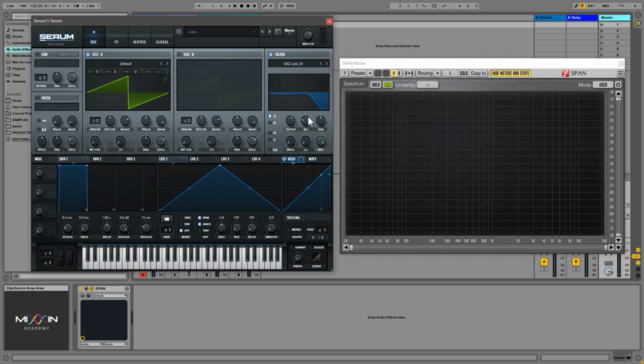Now, another really important parameter we have for a filter is the resonance. The resonance is the amount of boost the filter gets on its cutoff frequency point. Right there, where we start cutting off, if we do a resonance boost, we'll get a peak right before it starts gliding down. That gives us a characteristic whistling, resonant sound, and hence it's called resonance, of course, because it's upping the resonance.